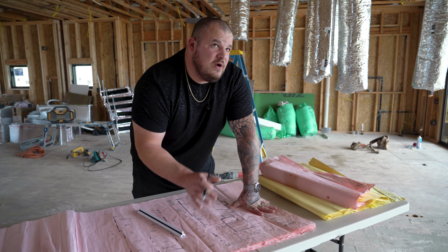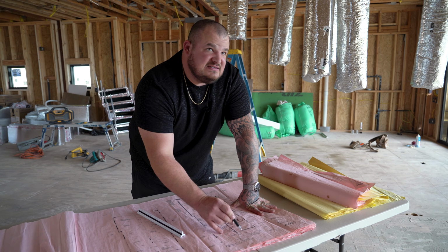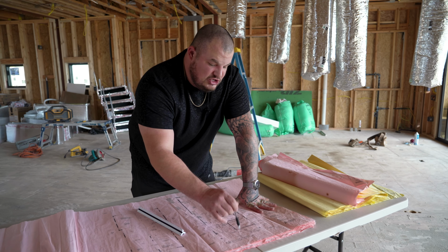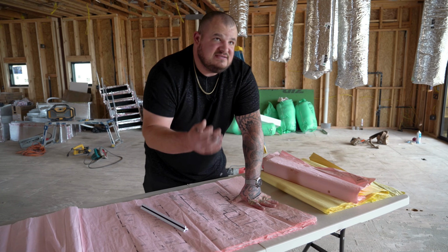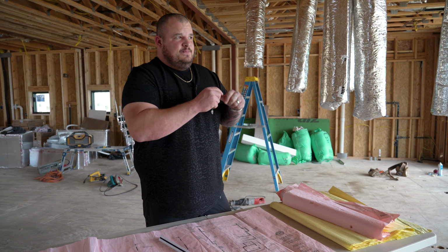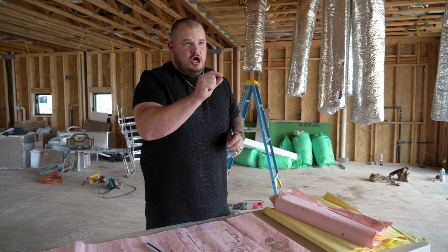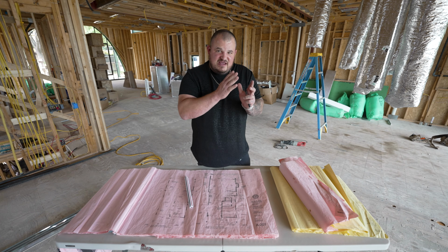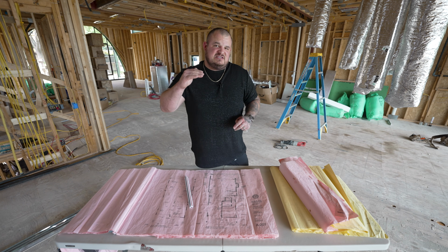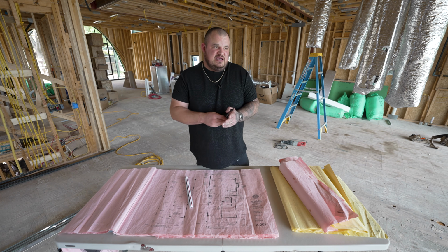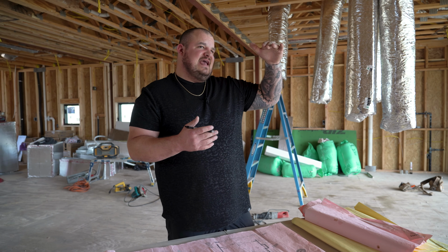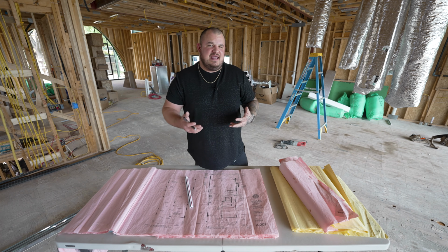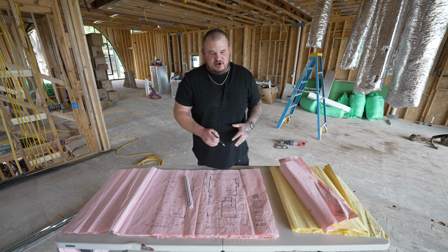Okay, now there's a couple different ways that these are noted in plans. Sometimes the sizes of the windows and doors are just noted directly here on the plan. But the best way is to reference the window or door schedule with a number. But now, sometimes you will see different sets of numbers, like 3068. That means a 3'0" wide door by 6'8" tall, which is a standard door size. Doors primarily really are 6'8", 8 foot tall, and 10 foot tall. Now you can get custom doors made in really any height, but that's normally what you're gonna see.